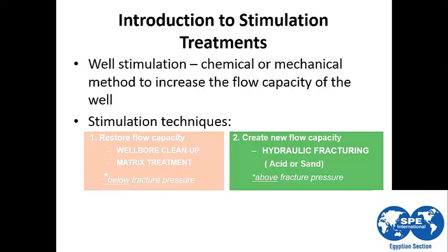However, matrix stimulation means we are treating the pore spaces of the rock, trying to dissolve the cementing material between the grains itself to increase the pore spaces. With this action, we will also increase the permeability, and this will affect the total skin value and make the skin value negative, because we are creating new passes inside the reservoir to allow the wellbore to reservoir fluid to pass through these passes.